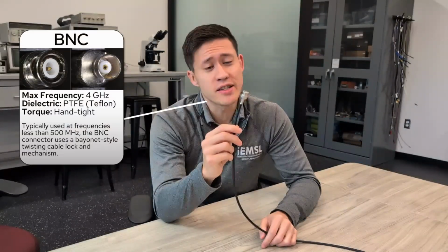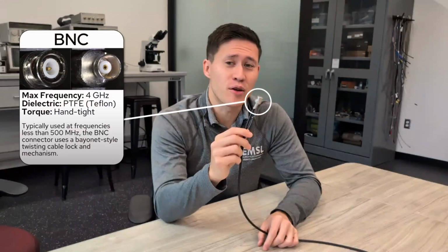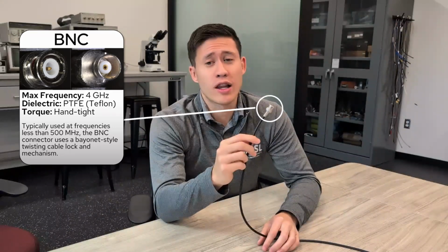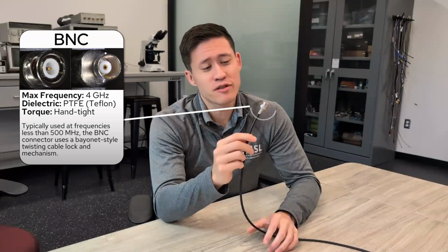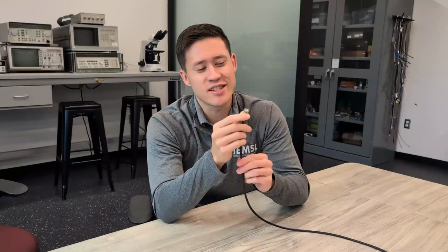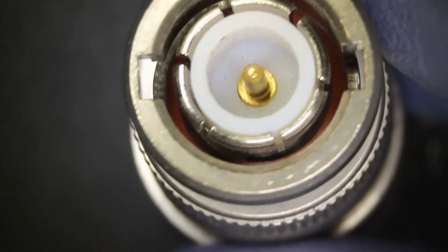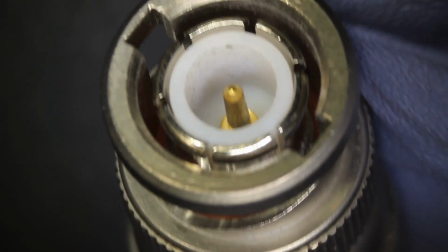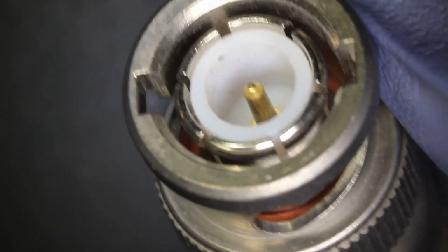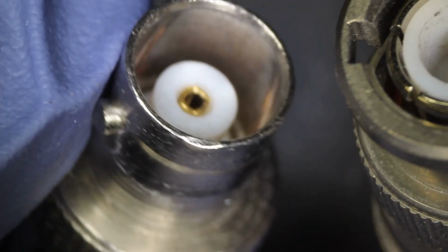The first type you might already be familiar with. This is a BNC connector. Now, this type of connector is often found on oscilloscopes, even some power supplies. For BNC connectors, you can expect reliable measurements and signals up to 4 gigahertz. And you can visually identify a BNC connector quite easily because it uses a twist and snap design with interlocking studs and slots. Here, you can see that the male BNC connector has this spinny bit on it, while the female connector has 2 little lugs on the outside.